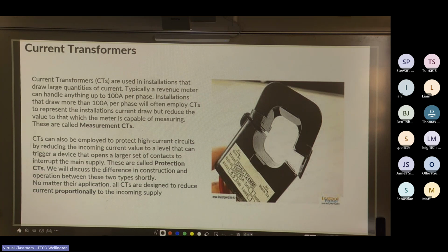One thing to remember, as my colleague pointed out to me earlier while we're having discussion, if you're taking a meter off for any reason, like to do a board upgrade, make sure it's unpowered first before you open it up, because if it's powered when you open it up, it sends a signal to the metering company that it's been opened. And it costs about $180 to get the meter resealed. And it's probably the same person who's coming to do your inspection, especially if you use Telfa Electrical anywhere in the Porirua, Wellington area.